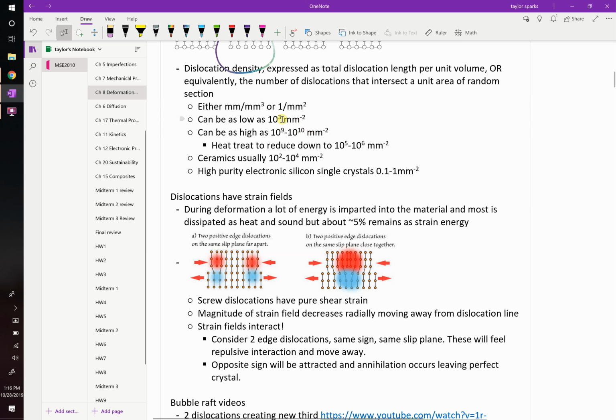So somebody explained to me, why on earth would dislocations go down when you put it back in the furnace? Why do we get rid of dislocations? Yeah. You give it thermal energy, so the atoms are allowed to shift a little bit. And if they had their druthers, they would find something of the opposite sign and annihilate and become a perfect lattice again. But it needs temperature for that to happen. So you have to keep on putting it back in the furnace.